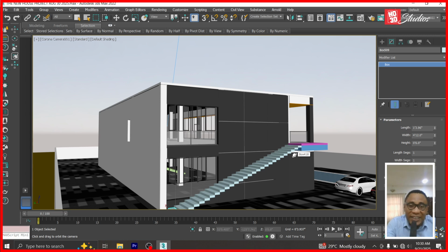But I just think 16 inches is all right because the average man has a foot of between 8 inches and 11 inches. Some people have a 12-inch foot, but it's quite uncommon. Maybe in the US where you have big people. So a 12-inch foot would rest comfortably on a 16-inch run.